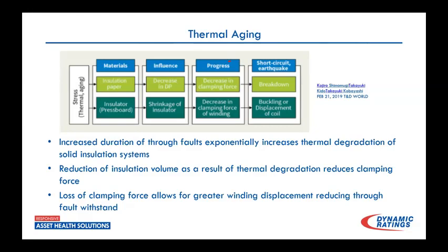within a timely manner after the event, a month, 2 months, you're really not going to understand the seriousness of how that heat affected that transformer, because gases tend to migrate pretty quickly into any type of headspace that's available. And of course, that changes. Hydrogen's very fast. Ethylene slower, acetylene slower, but they still do find their way out of the oil over time. And so you really don't understand how that transformer was affected unless you have a 24-hour sampling or monitoring of DGA going on.